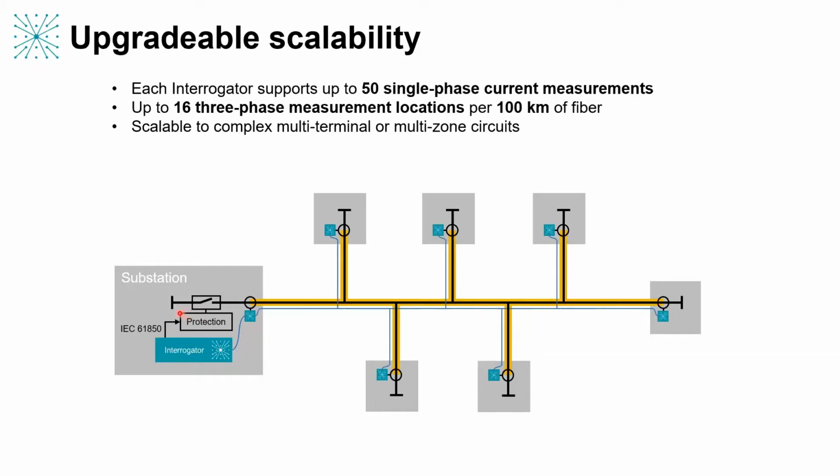But part of the power of this system is that it uses the 61850 standard in the way it's designed to allow that interoperability of multiple different systems. So we can work with the protection relays from all the trusted manufacturers like GE, like ABB, like Schweitzer, to allow them to protect a wide area or a multi-zone or multi-terminal system better.